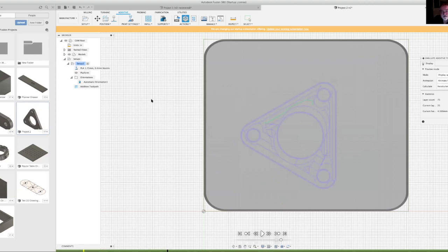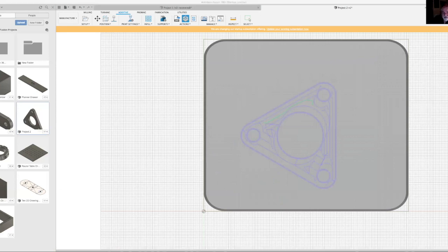Is that what you have? Yeah. You have a hobbyist license? Yeah. When I went out to get, what I had to do is get the new slicer. The old slicer had a bug in it. The original one that Fusion brought out had an issue where basically it didn't level the bed and it didn't zero the machine, and it didn't preheat the head. But all those things have been fixed because I actually did a little bit of research before this, and I wasn't going to show this, but let's see.